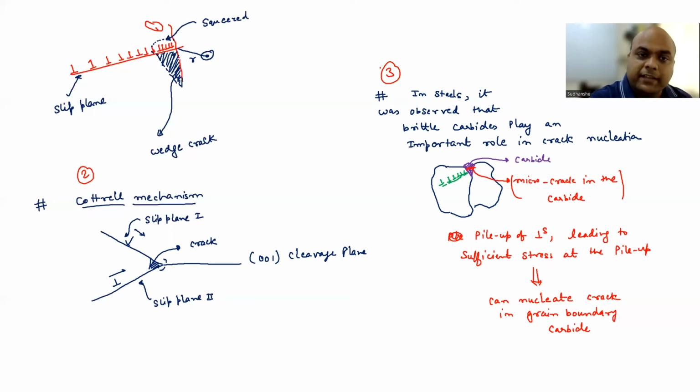When they grow, they are going to generate different patterns. Like in ductile fracture mechanisms, we talked mostly about dimples, right? And tunneling also, that is like macro. The dimples are micro, right? Similarly, when we talk about cleavage fracture mechanism or brittle fracture mechanism, we have different patterns if you look at the fracture surfaces.